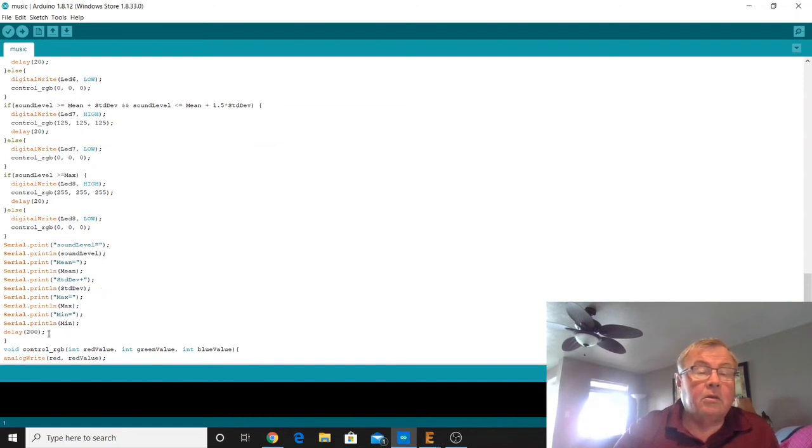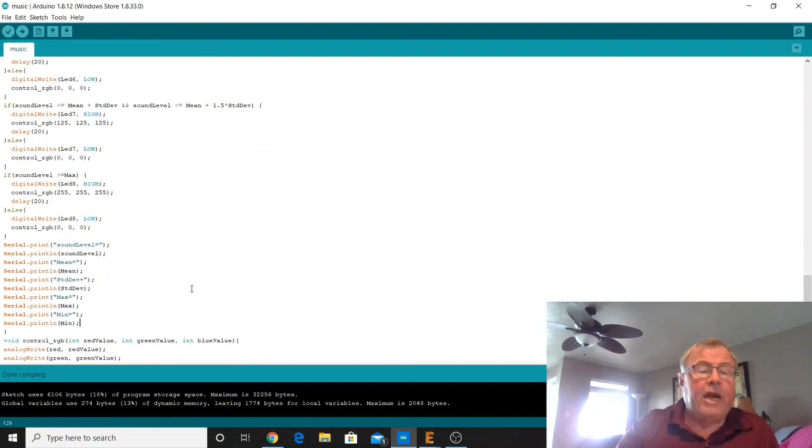You can make this dance better if you get rid of that 200 millisecond delay, and I think I will get rid of that 200 millisecond delay, and do a save on this and do a compile. And it's compiling my sketch. And once it's compiled the sketch, it'll come back and say done compiling, and there's no errors.